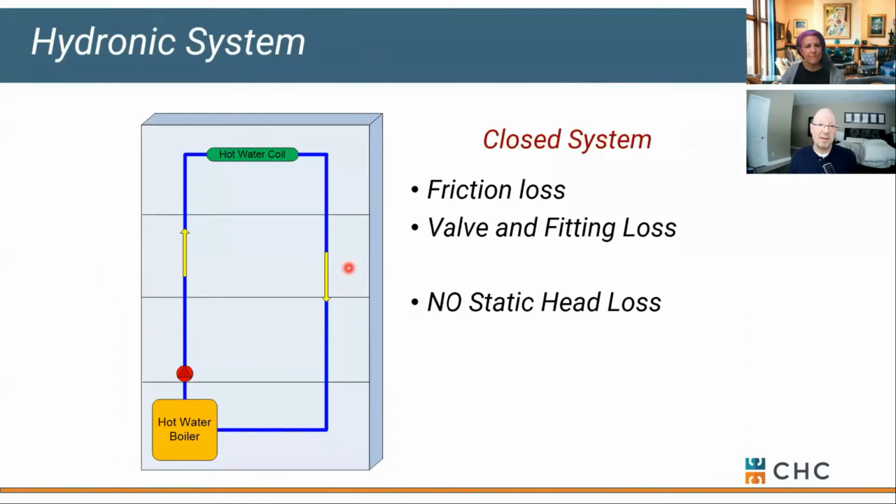First off, let me start by covering some definitions or fundamentals, if you will. Most of what we do in a hydronic system is considered a closed loop, meaning it's water running through pipe, and we fill it at one location. We add water to the top of our building, and then we can start to circulate it. We turn a pump on. The beautiful thing about a closed loop system is what goes up also comes down. So our pump in this case only has to overcome the friction loss in the line or our pipe, and then we can start to circulate water.